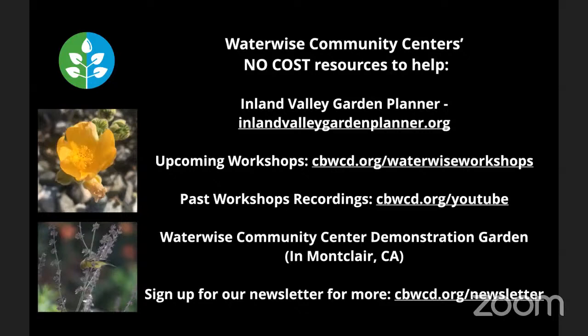And then the valves, the way the irrigation controllers work is that they only run one valve at a time. And so as long as all those valves are connected to a single water source that's reliable, then you can have as many valves as you need. And then you purchase an irrigation controller that is already set up to accommodate the number of valves you have.